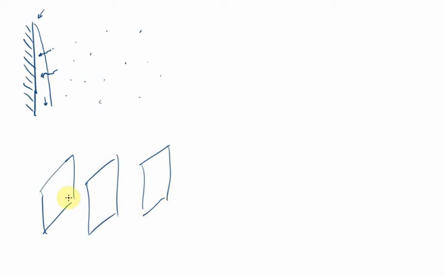And you might choose to do this for simple cases like absorption. So if we have walls with enough surface area, and you might think about creating a system with many plates, for instance. So if we create a plate or a row of plates here, and we wet all these plates with some liquid, then expose all those plates to a gas, then we can start absorbing from the gas onto those plates, right? Simply through absorption into the film that's sitting on those plates.